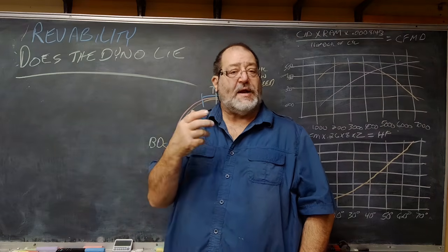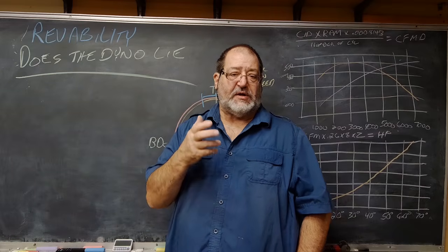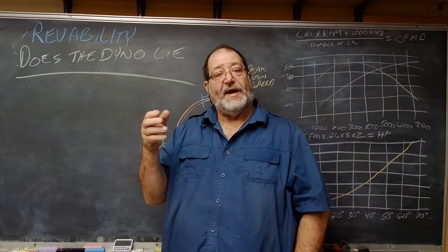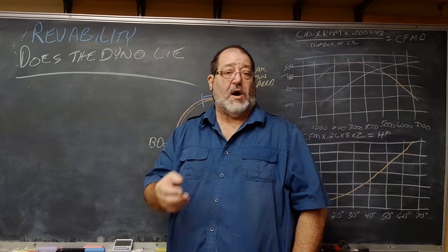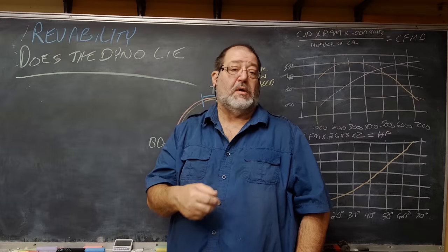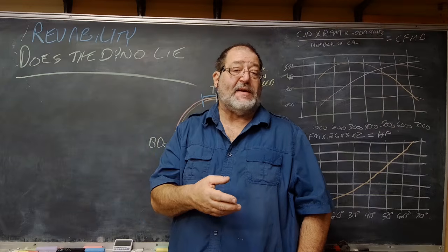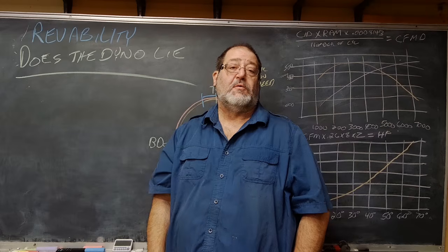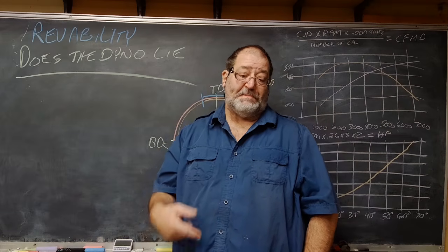On a dyno, when you run it, the dyno is actually controlling the rate that the engine goes up in RPM. You can set that: 150, 300, 600, which is fairly normal, 1200, which is kind of fast. 300 is not a bad number, it's a little slower. Courtney did the 150 rate on me at one time, and man, that's a long pull.